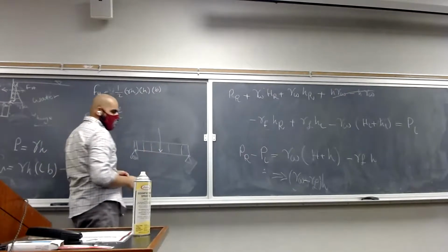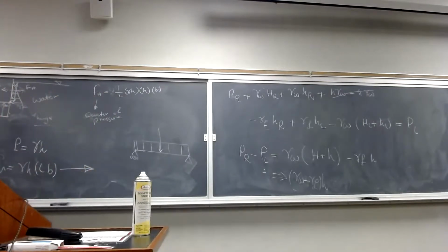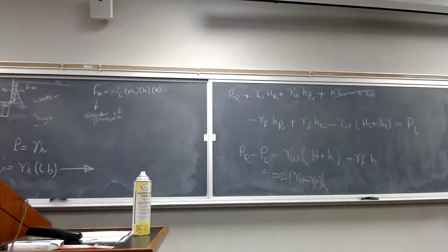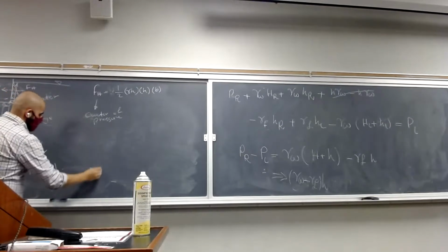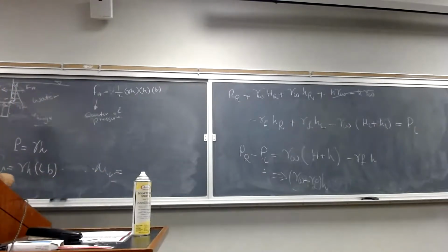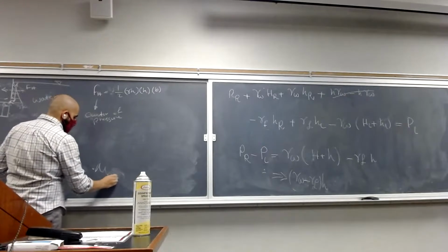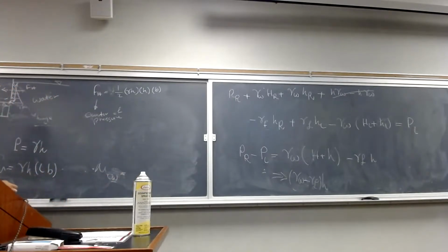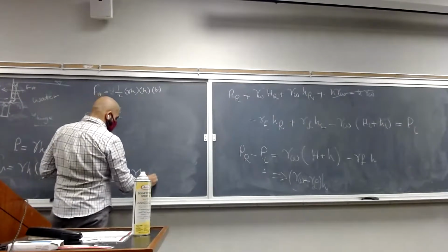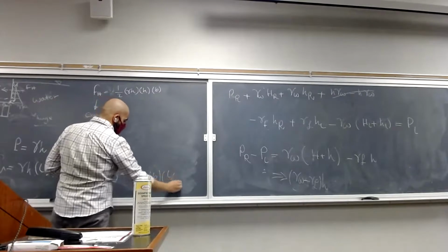So the resultant force is essentially passing through the center, which is going to be L/2, and the moment it is creating, let's call it M of vertical, is the clockwise moment, which is going to be gamma H L B multiplied by L/2.